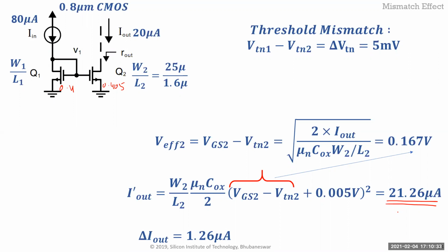Okay. So that's all I want to cover with simple current mirrors. So I think hopefully that's given you how to do small signal, what's the motivation behind doing current mirrors, serves both as your bias as well as your active load for your amplifiers or source followers or whatever you're doing. And then how did we create a simple current mirror? And now the complex current mirrors like the cascodes, the wide swing cascodes are just building on top of this, basically. Same principle, we're just trying to improve them.